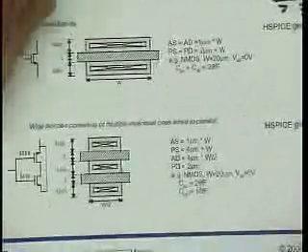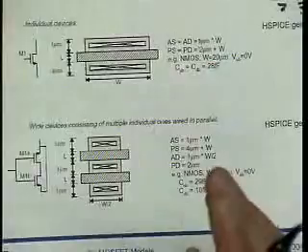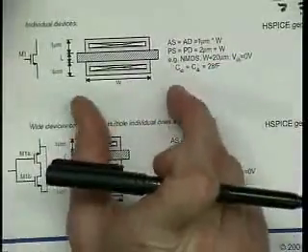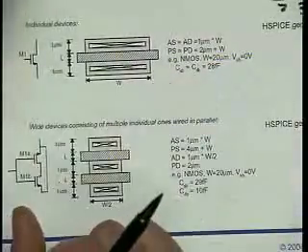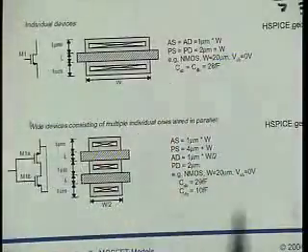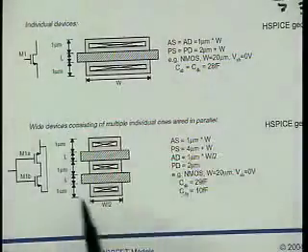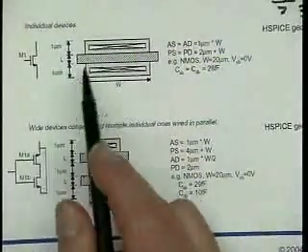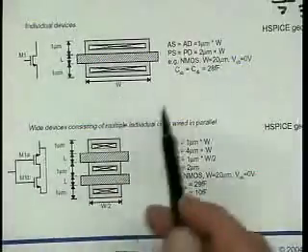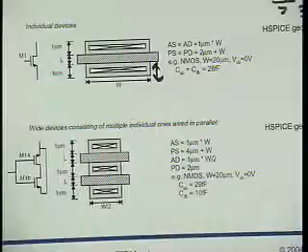Okay. So let's look at different layout choices. Here, let's say that we needed a device that had a certain width W and a certain given length, maybe 100 microns wide and 1 micron long. Well, we could lay it out like that, and then we get, of course, source and drain capacitance. That's W times whatever this thing is. In our process, the minimum is 1 micron, right?